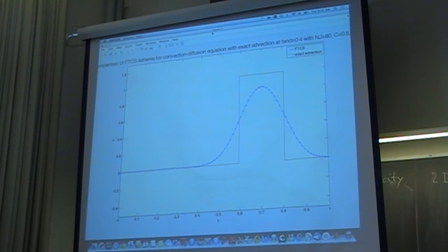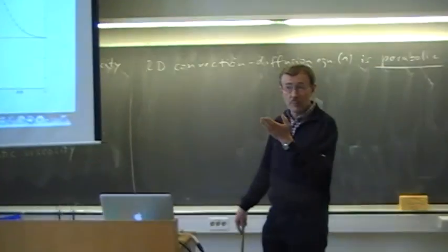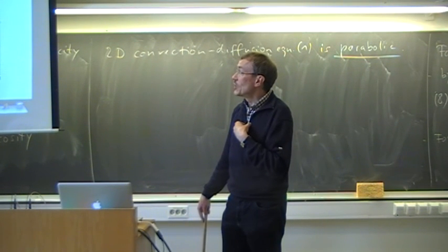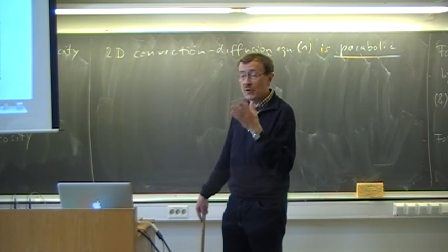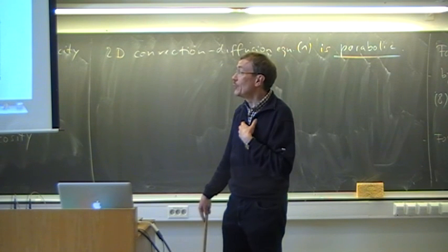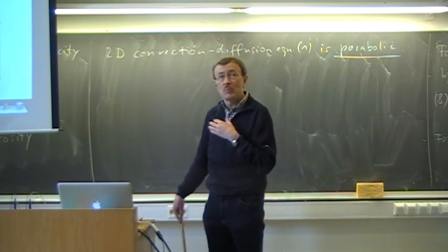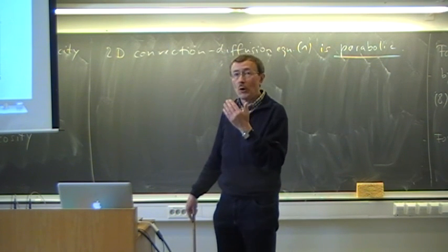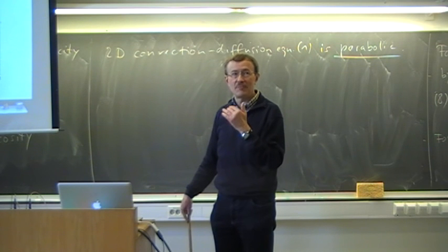Therefore, we'll discuss after the break how to discretize that, and also to estimate the error that we make when we do the discretization. That is actually the problem that we face when we do the discretization, that we will have some numerical diffusion present, but this should be as low as possible in order not to spoil the physical diffusion.